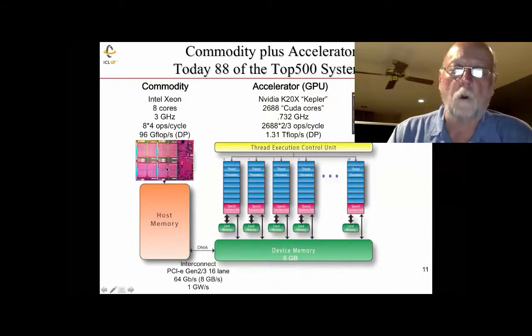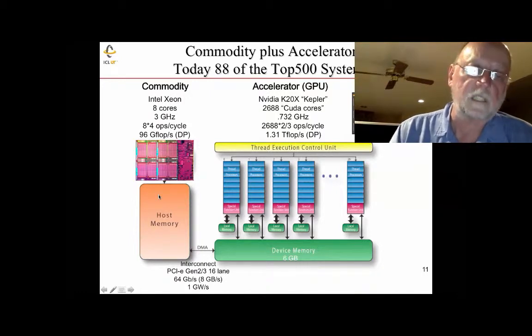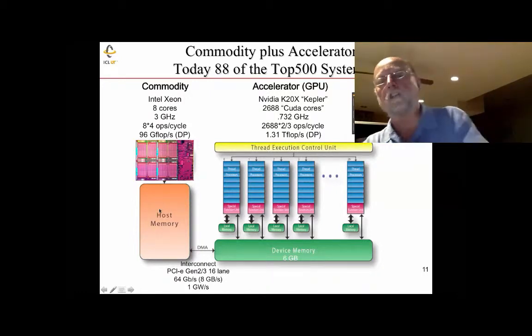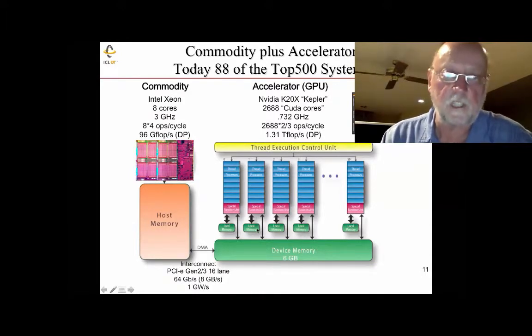The host program then tells the accelerator to do something, to run a program that executes with the memory that was placed over on the accelerator. So it does some operation over here on the accelerator. In the meantime, the host processor can go off and do something asynchronously. So it can do something and later check to see, in fact, if the data is ready, if the computation is finished on the accelerator, and then drag the data across this link here between these 2 memories.